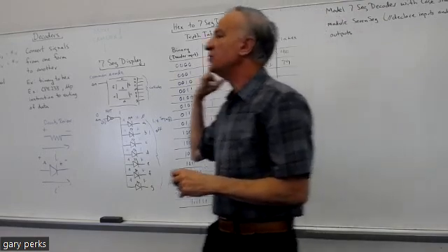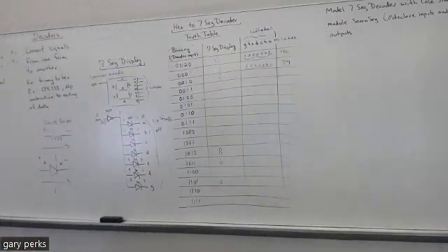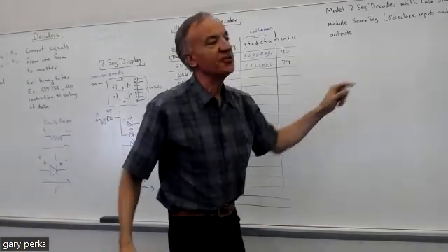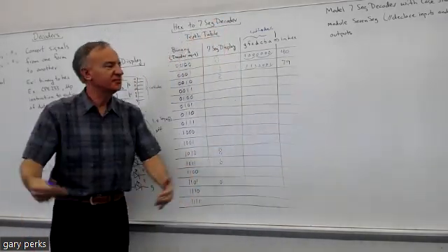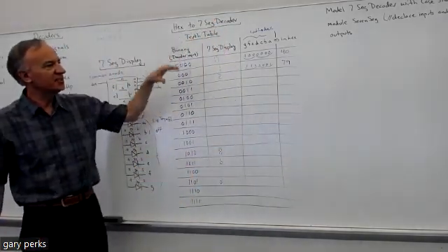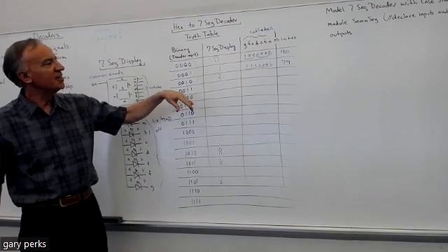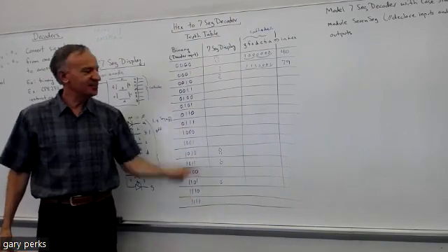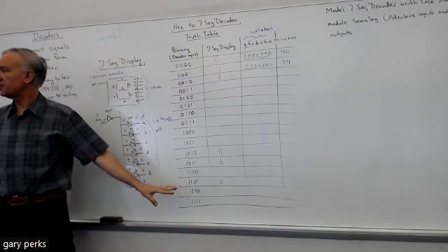And then when you go to verify on the timing diagram of your SystemVerilog to make sure this is working, because when you build this decoder in Verilog, which you'll be able to do today once we're done here, you're done with the activity. How many test cases are you going to have for your decoder? 16, because you need this whole truth table.